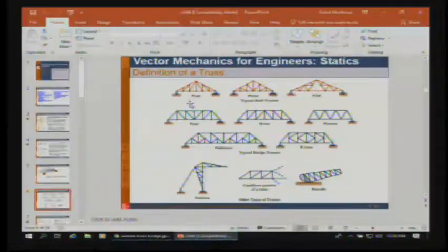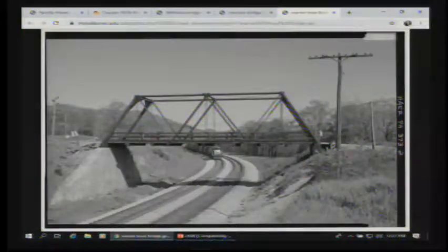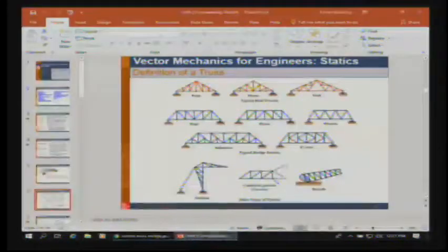So the kind of trusses that we looked at for the bridge tended to be Warren trusses, where they're just sort of like M's all the way through. If we take a look at that, you see how that's just a perfect little chevron shape. So, Warren truss. But Warren, Howe, and Pratt trusses, as well as this, which is called a Baltimore truss or a K truss, are all bridge trusses.